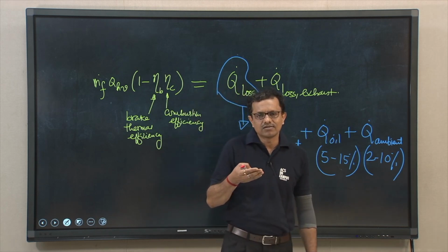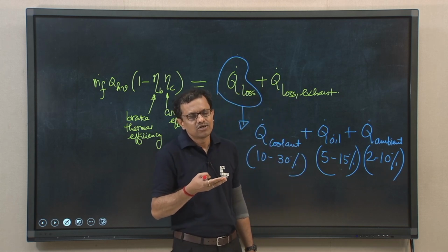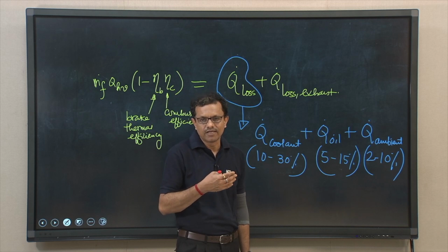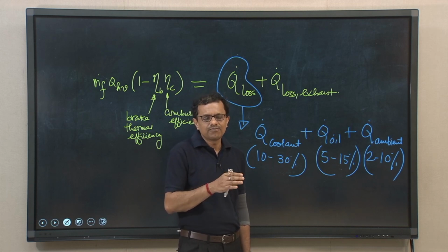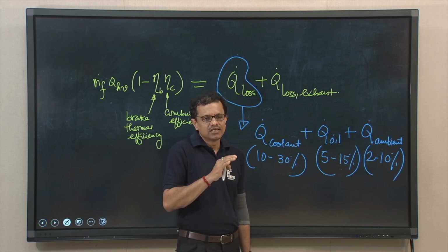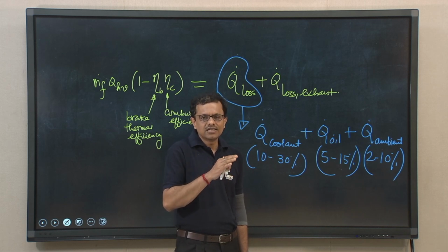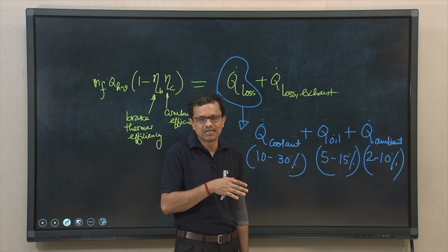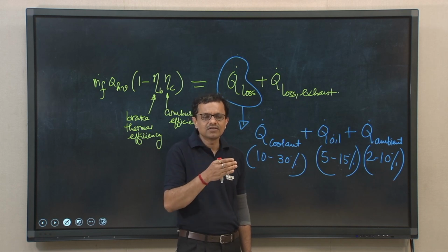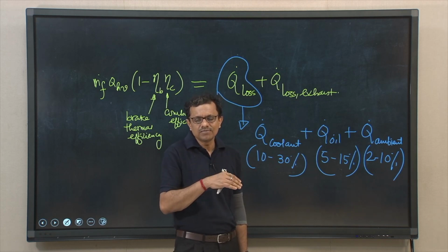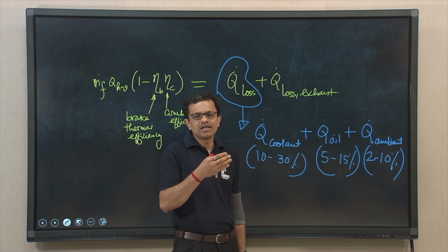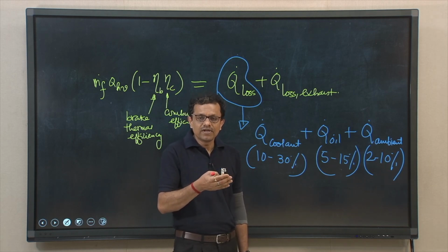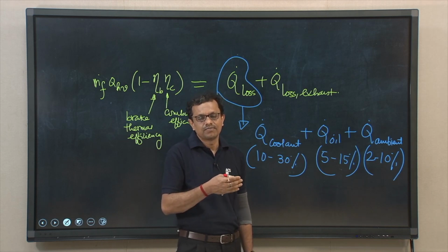As I said, combustion is the process through which the rise in temperature inside the cylinder is of the order of 3000 Kelvin. We should have proper design, and the engine should have some arrangement to remove a substantial amount of heat from the engine cylinder, to prevent several mechanical components from overheating, from possible failure, in fact from melting.